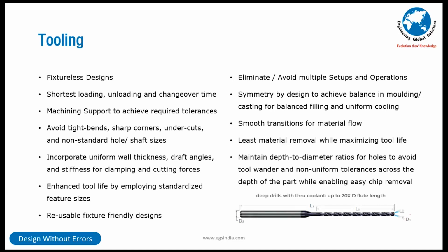The stiffness of the component has to be such that it's not compromised. Avoid tight bends, sharp corners, undercuts, and non-standard hole and shaft sizes. This is absolutely required, especially the last one. Non-standard sizes should be avoided. Why? You can buy it from the market and put it in. Design it for what is already available.